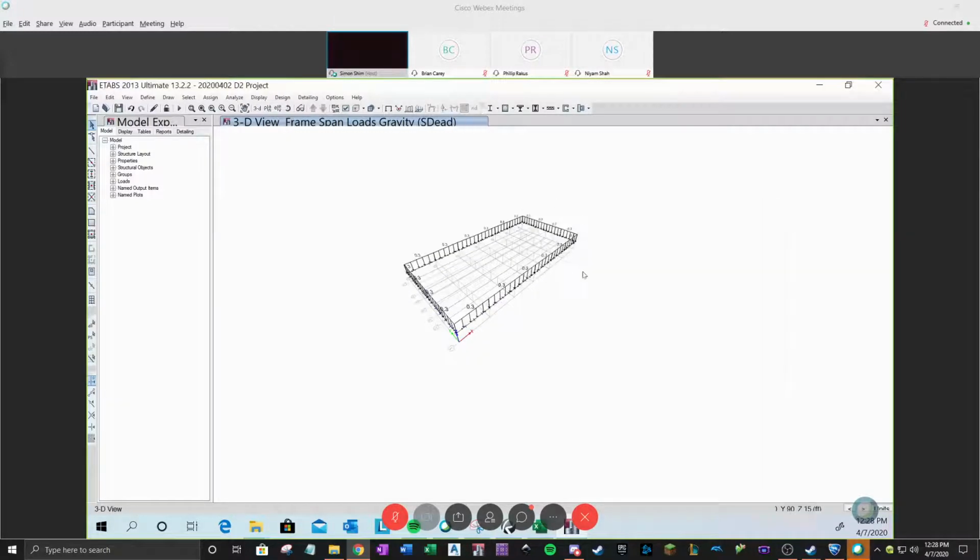So okay, you see that additional curtain wall load. So we have composite dead load on the slab 20 PSF, live load 100 PSF, and also line load on the perimeter only, 300 pound per foot. Depends on the material of the curtain wall or enclosures, obviously. So I think we are ready. I'm going to run it. Right click, you could just turn all the objects on.